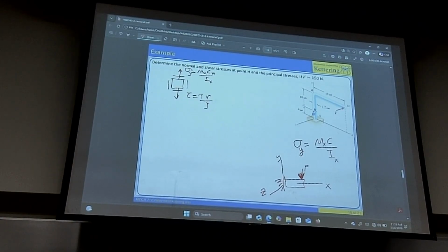You gave me one response for X, and let me give you the point for that. Evan, moment X. Look at the force. Look at the axis X, Y, Z that is at the centroid at point H. You know the moment is force times arm, right? For bending, what's the arm? From the force. Yes. What's the arm value? What's the arm length? 18 centimeters.